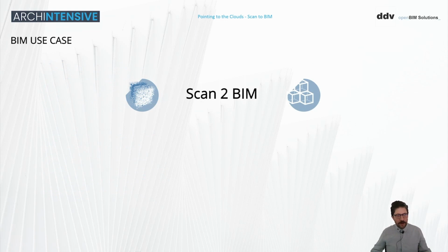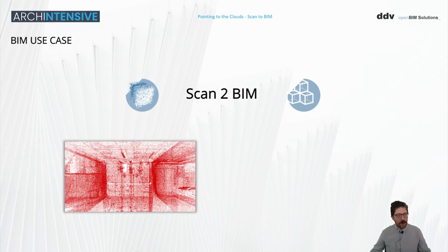As I told you, this use case that I'm going to show you is scan-to-BIM 1, which means that in the very beginning we receive laser scanning data, which we have to process. And once this process is done, then we are able to start with the information modeling within our native environment, the Graphisoft Archicad one. So we receive things like this. So it's a point cloud.